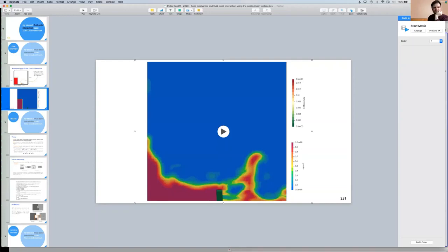When we use a static mesh, does it mean that the solver assumes the deformation is very small and always solves the deformation on the original mesh? Yes, the short answer is yes. If the deformation is small, that's a fine assumption. One comment is that some of the nonlinear geometry solid models have hard-coded the mesh motion into the solver, so you might see that static FE mesh is used, but actually it's not really static. It is moving the mesh, and you see the mesh is moved. So it's on my to-do list to extract that code out and put it in an OpenFOAM-format dynamic mesh, just to make it clearer.